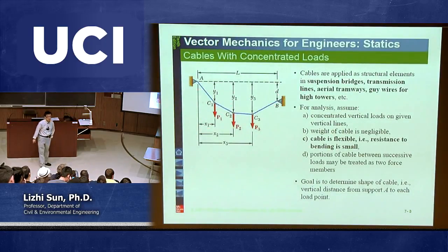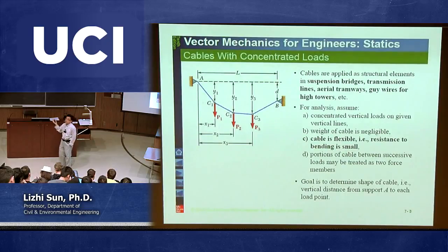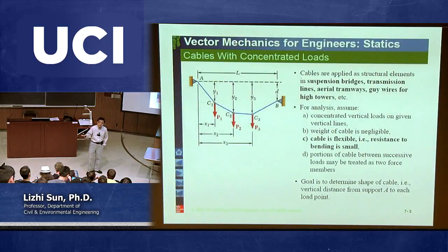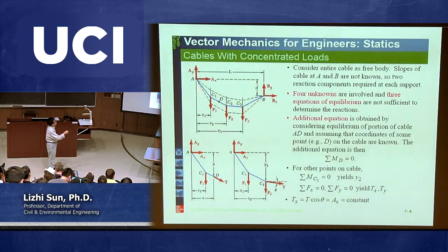to calculate the reactions. And we know that in chapter 4, or even in chapter 6 and chapter 7, how are we going to calculate the reactions? That's supposed to be simple. We just cut those reactions, right? We cut point A, we cut point B, and we plot the free body diagram. Let's follow what we have learned. So this is the cable AB again. We cut point A, we gave two reactions,